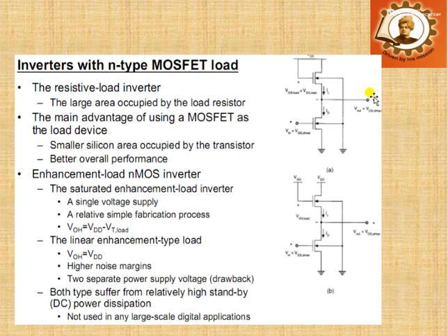The pull-up MOS is always in saturation, so Vout is not exactly equal to VDD, because there will be a voltage drop across this MOS, which is nothing but its threshold voltage VTH. For full swing, if the input is in full swing, the output will be VDD minus VTH, due to the saturation mode of the pull-up MOSFET.